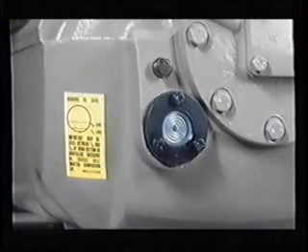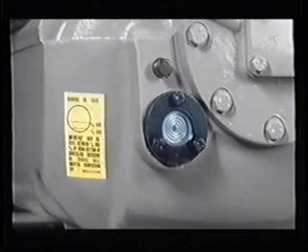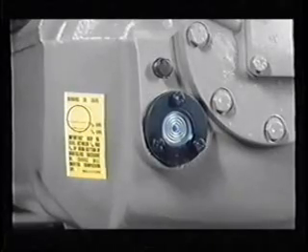It's also possible to partially fill the motor housing with oil. This condition can cause liquid slugging at startup, increasing the possibility of mechanical problems such as blown gaskets, broken valves or rods, and so on. If the sight glass is full, oil is being forced out through the orifice, which could cause a problem. It's important, therefore, to keep oil levels within recommended limits. It's also important to use the correct oil to ensure reliability.